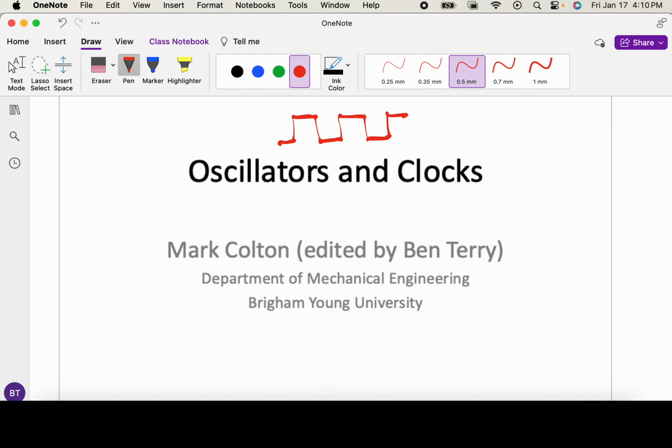So our particular PIC, or microcontroller, has what's called a fast resistor capacitor, or FRC oscillator on board. And it uses a resistor capacitor circuit to generate a stable clock signal without requiring some external crystal or resonator. You can actually use an external crystal or resonator to give a very precise clock signal. Unfortunately, the FRC is not very accurate.